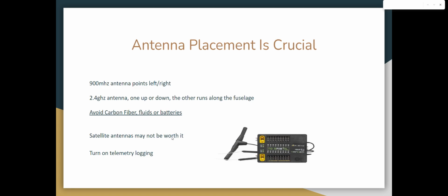And then the other thing I'll mention is satellite receivers will work with this. You can hook up, for example, on this TD-SR18, a TDMX, a TDR10, TDR6, whatever you feel like. In pin 1, you change that to S-Bus in and you use S-Bus out on those other receivers. It all works, and you can get a satellite receiver. The only downside with that is that when you do it with 2 receivers, you only get the telemetry from 1 receiver.